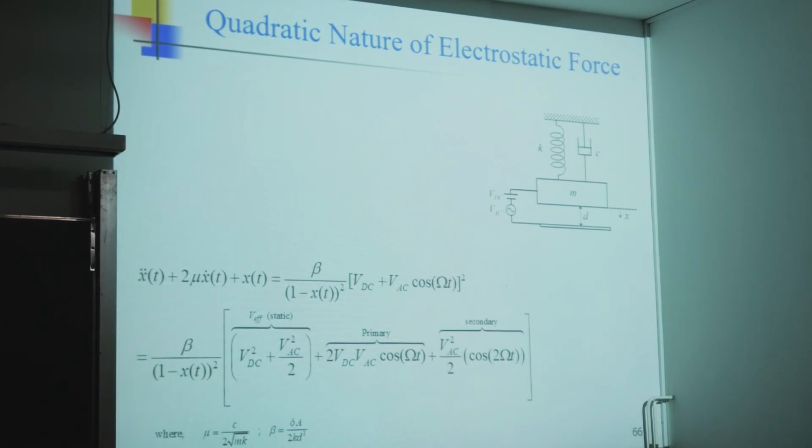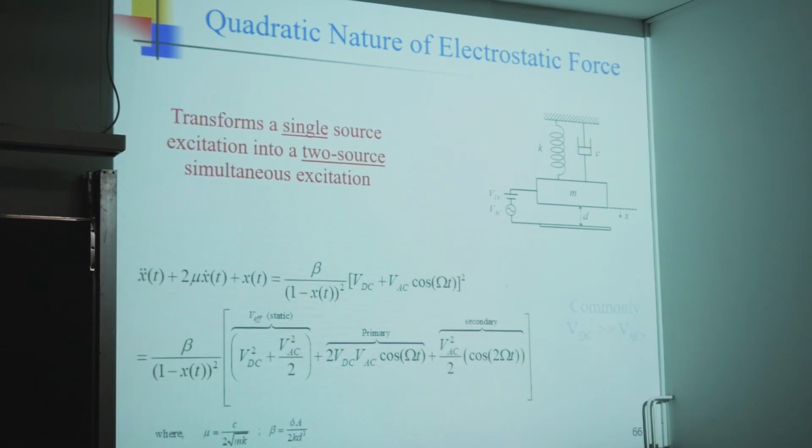So let me explain the idea more. Here, what I would like to say, I'm going to rely on this component to achieve logic. So this is a schematic showing that I'm proposing to use input logic VAC cosine omega t from a certain unit, and from the other unit VAC cosine omega t. Then the electrostatic force comes and squares this, converting it into cosine 2 omega t. These systems have quadratic nonlinearity, so they can already be excited at subharmonic resonance when you excite them at twice the frequency.